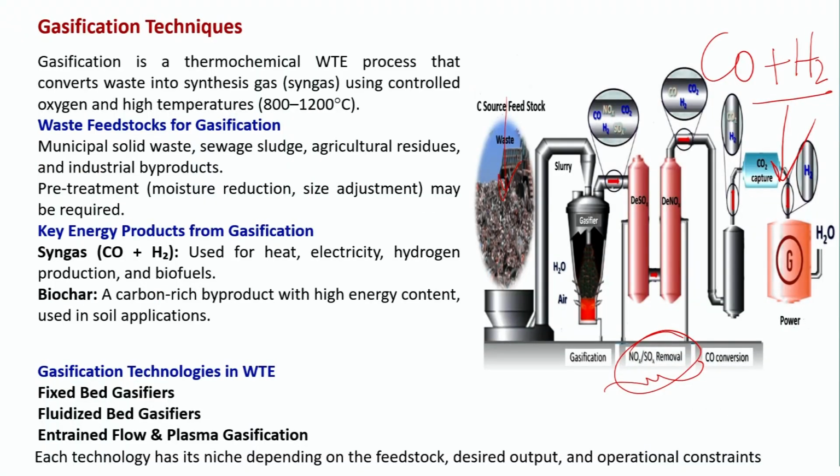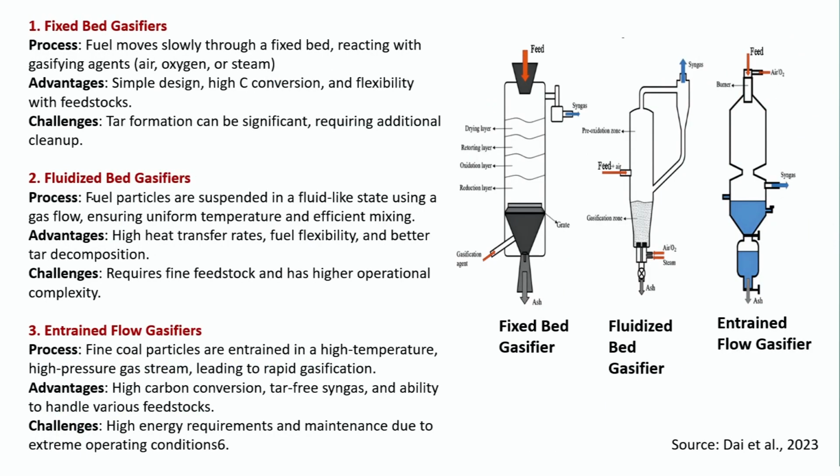I mentioned those different technologies, whether fixed bed, fluidized bed, entrained flow or plasma gasification, and this is the structure of how they actually work. In a fixed bed gasifier, the fuel moves slowly through the fixed bed, reacting with the gasifying agents, air, oxygen or steam. This is a simple design, high carbon conversion is possible, and there is flexibility with feedstock. Even a mixture of feedstocks or waste materials can work. The challenge is that tar formation can be significant, requiring additional cleanup, so we need that sophistication for cleaning up the tar as well.